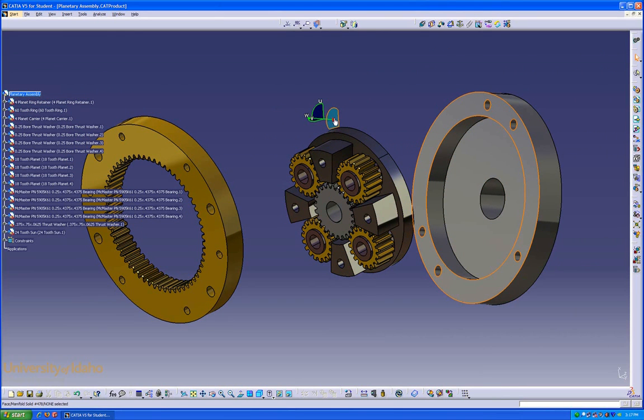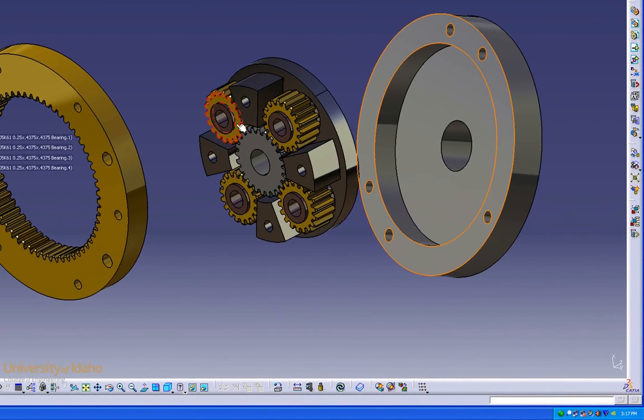To remove the compass from all the parts, just drag it out into the workspace and it snaps back to its home position. The update command at the bottom of the screen can be used to snap everything back into place with respect to their constraints.